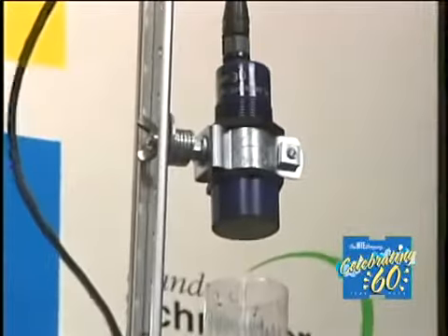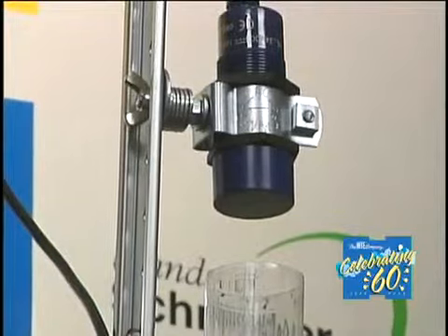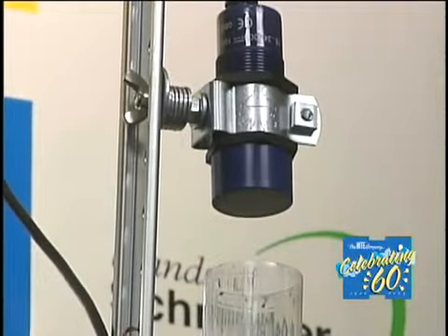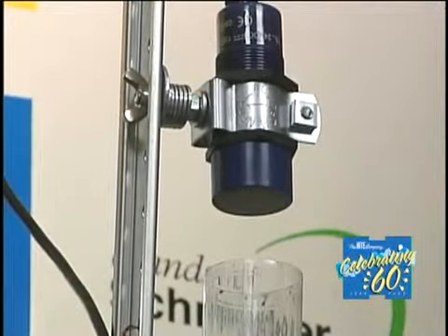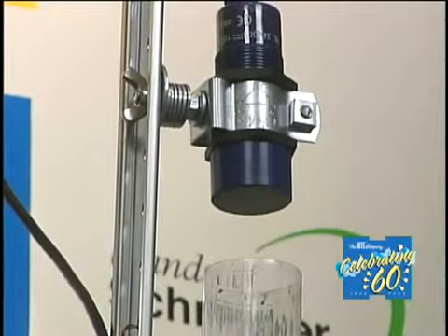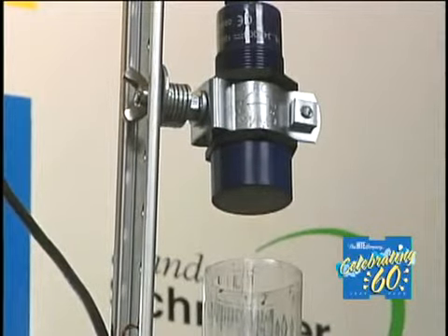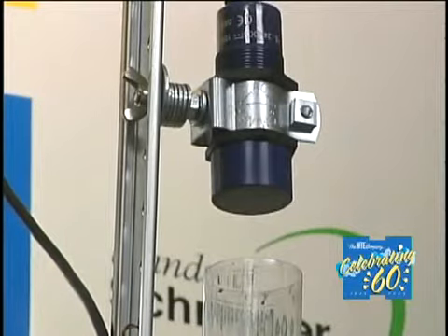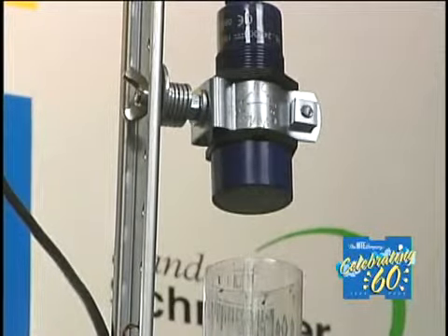So to get the feedback, up on the top of this tube, we have an ultrasonic sensor. The sensor is able to detect where in the tube the pill bottle is, and then it gives a 4 to 20 milliamp signal proportional to where the pill bottle is in the tube. It sends that 4 to 20 signal to the drive for feedback, and then the drive essentially mirrors that feedback signal to the display, so we have an indication on the display where the pill bottle is.